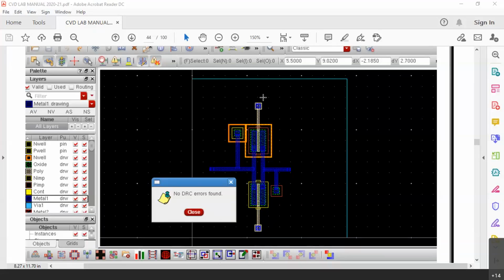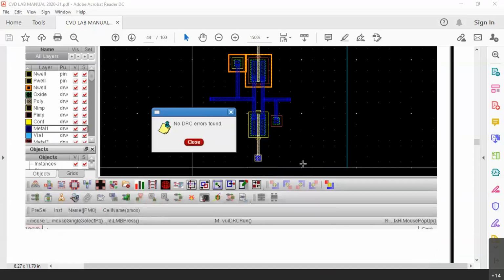Otherwise, the Pmos gate is connected with the complemented input of the Nmos gate's input. And later on, you have the regular input signal. And output is taken here at the right side. All those are metal connections. So this is the layout. Layout is really very simple.